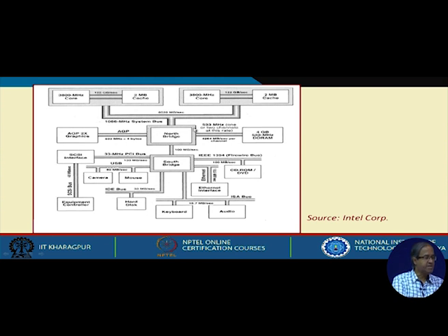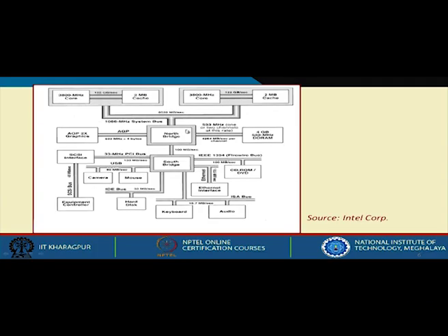And here you can see is the north bridge. I am not sure whether you have noted this: when you buy a computer system, or look at the specification of a PC, it does not only talk about the processor and the clock, it also uses a code name for a chipset, like Intel this chipset. Chipset actually refers to the north bridge and the south bridge combination. What are its capabilities, what are its speeds, and so on. The chipset will determine that. So, this north bridge and south bridge taken together is the chipset.